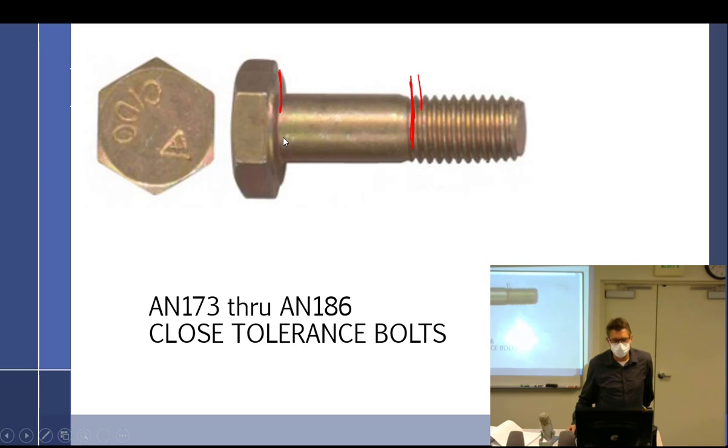Most of the time, I want to say they're not CAD plated right here. I think the CAD plating is actually off of it because the CAD plating is an unknown thickness, and they want it to be the exact right size. So this one indicates that it is CAD plated, but I've seen more expensive ones not CAD plated, and it looks like somebody took a bolt, stuck it in a mill, and actually precision ground it to the right size. So a bolt like that's going to fit exactly in that fixture I'm talking about and allow no slop.